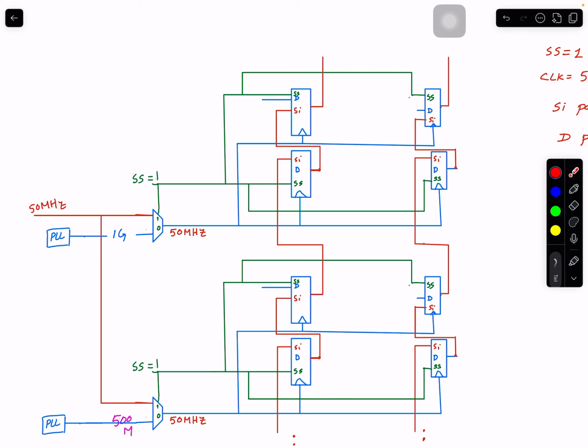Maybe the number of flops, both are 50,000 and 50,000, their latencies are coming together, and it may not be a problem. So the question is, are you making sure about any path? Now, one other thing I'm telling you: this is a typical case where your chip is back and you're going to run only in this mode, scan shift or functional. You're not going to run your chip at the same time for both. But in your pre-silicon validation, you don't want to have multiple timing runs.